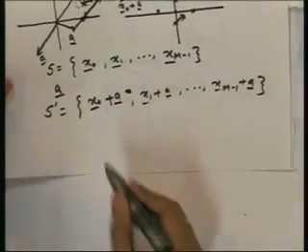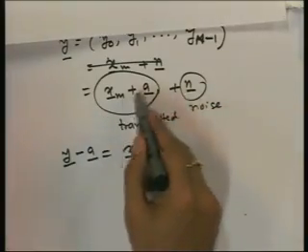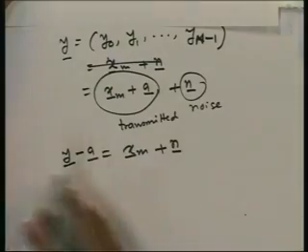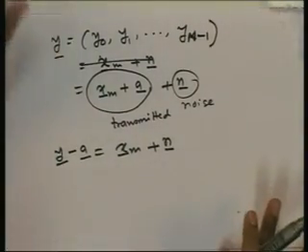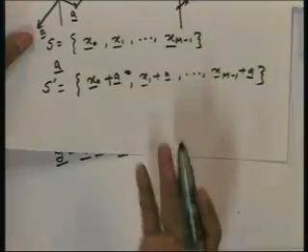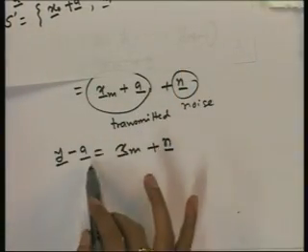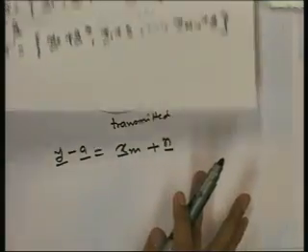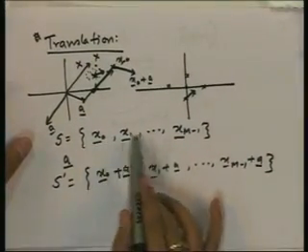So, if we transmit this signal set, and if we then receive this, that is this plus noise, then we can simply subtract A at the receiver from the received vector, and then we can assume as if this signal set itself was used by the transmitter and we have received this. It is the same situation as if we transmitted this. So, the only thing we need to do is just subtract A, and then we can do the demodulation just similarly as we would have done here.